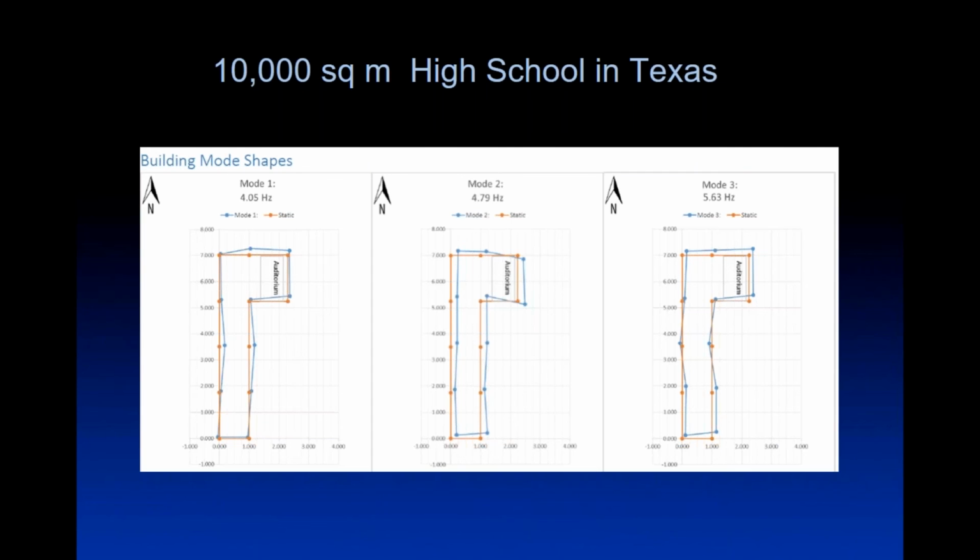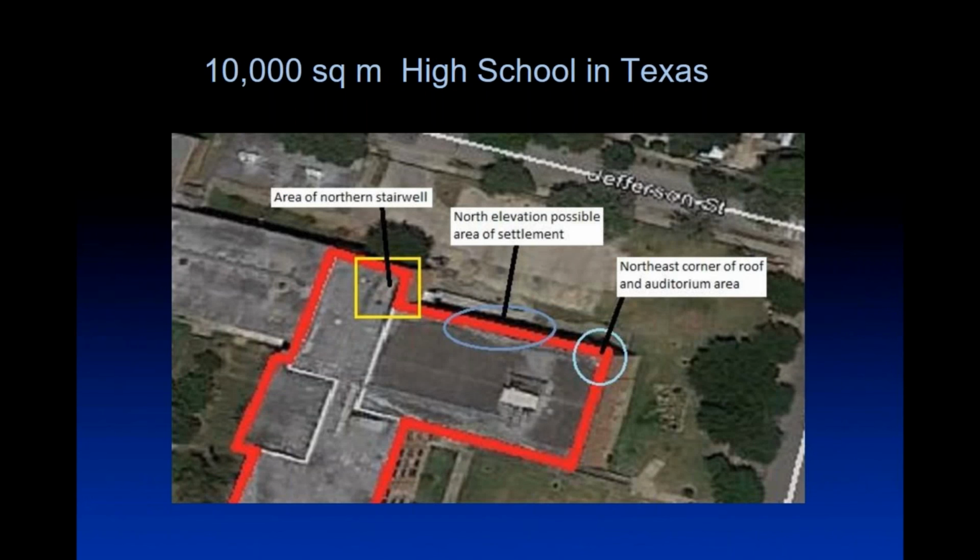But additionally, while I'm on this, look at this. In this particular case, we were measuring vertical vibrations as well as the X and Y, and we found 3 positions around their auditorium where the vertical response was larger. So we reported this. We didn't know why, but we said we've got 3 areas here which we've fingered. We're saying something's going on here. And they said, oh, we wondered if there would be something because we had timber piling underneath here, and then we had flooding, and we were worried that perhaps it had degraded.